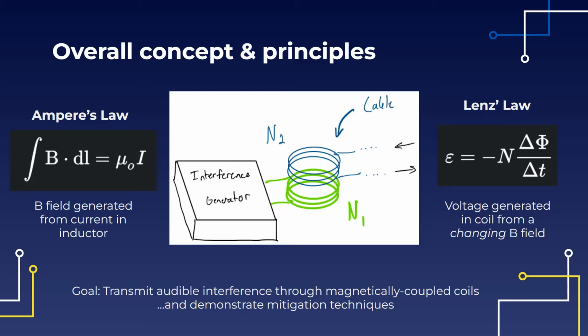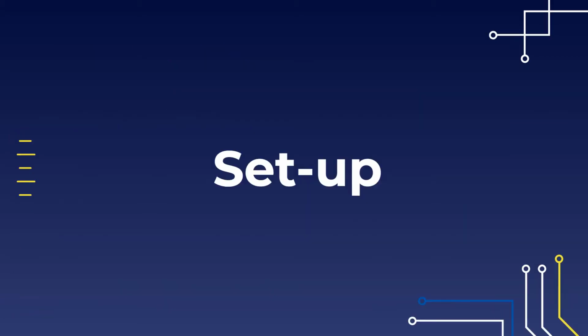We accomplish this by creating a sine wave current through the inductor through the use of an LC oscillator. This circuit will charge up the inductor to a predetermined current, then allow the inductor-capacitor loop to oscillate at their natural frequency, producing a B field with the same frequency.